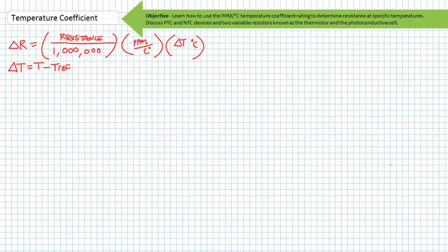This is meant to simulate an increase in temperature or molecular vibration of a structure. As temperature increases, vibration increases, and so does the likelihood of an electron colliding with another particle. In short, it's harder for current to go through a hotter resistor because it's running into a lot more moving particles, i.e. the resistance has increased because the temperature has increased.